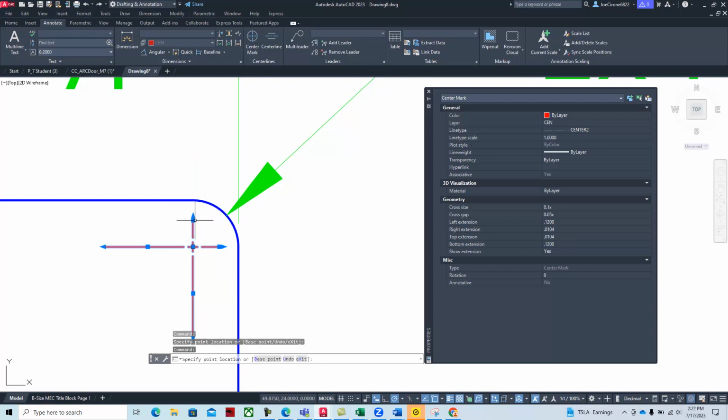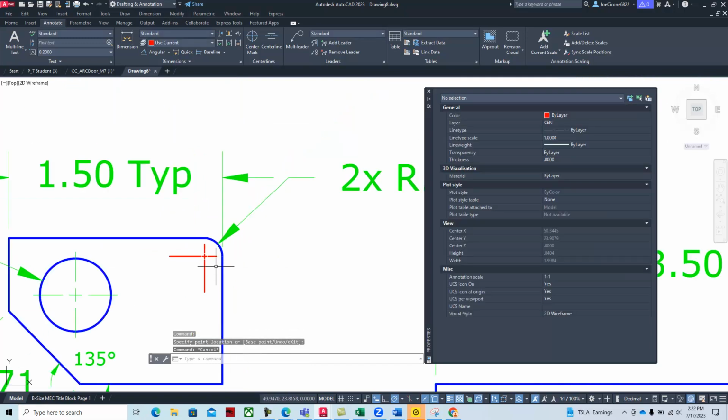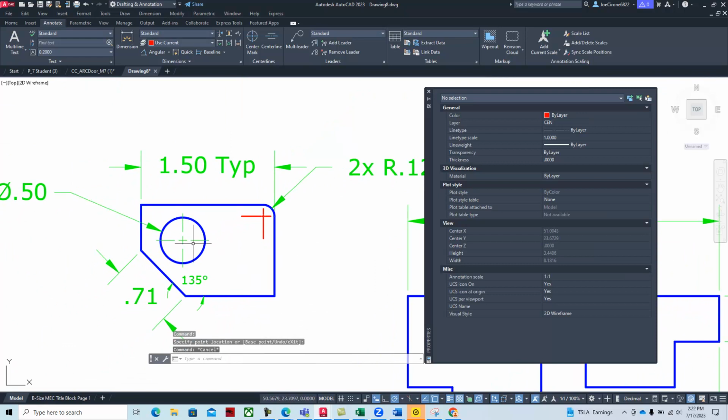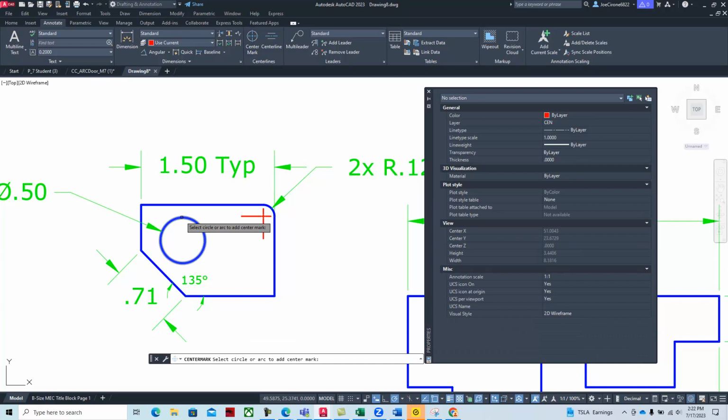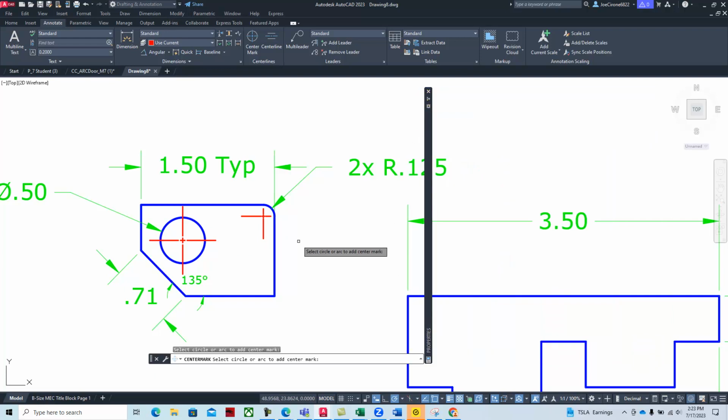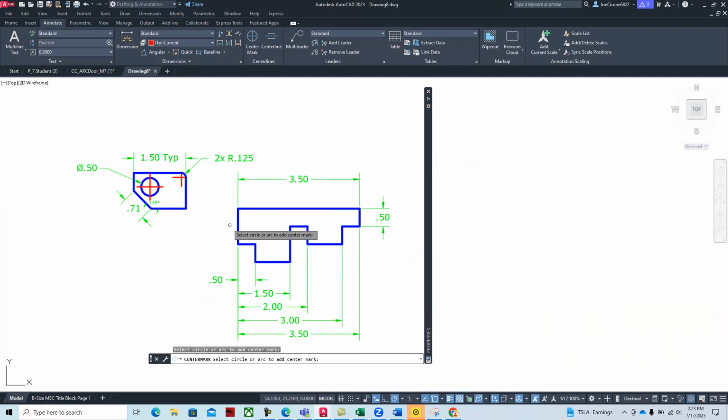As you see fit for annotation of drawings and dimensions. Same thing with this. If I click on this and then I say, get rid of the center mark, say none, I can then go back and put it in with the center mark tool. And it looks better. You can right away see that it's targeting the center of that hole. And so that's what we want. We want drawings that are easy to read and to interpret.